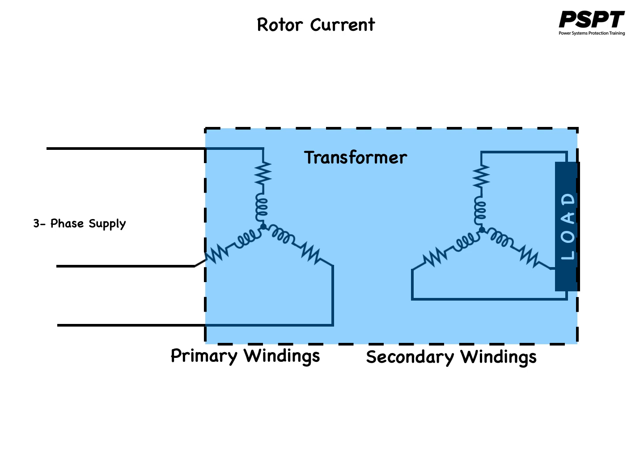An induction motor may be considered to be a transformer with the rotating short-circuited secondary, or an electric load equated to the mechanical load of the motor. The stator winding corresponds to the transformer primary, and the rotor winding to the transformer secondary. However, the following differences between the two are worth noting.